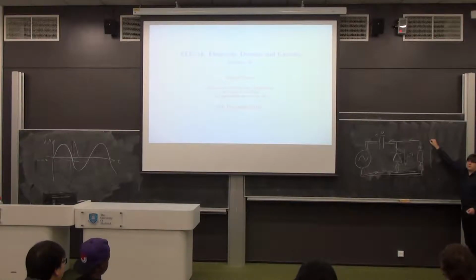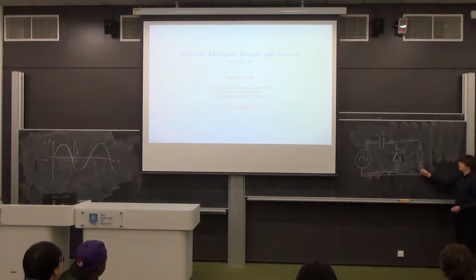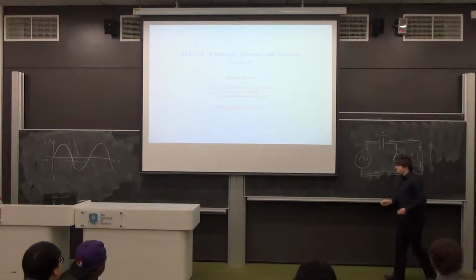We call this positive output, and we call this negative output. If you prefer to say that this is the output that I think is important and this is my reference, then it'll be 0.7, and that graph should just be flipped. It's entirely up to you, but usually we would call this negative clamp because we like to think about the references being at the bottom of the diagram.